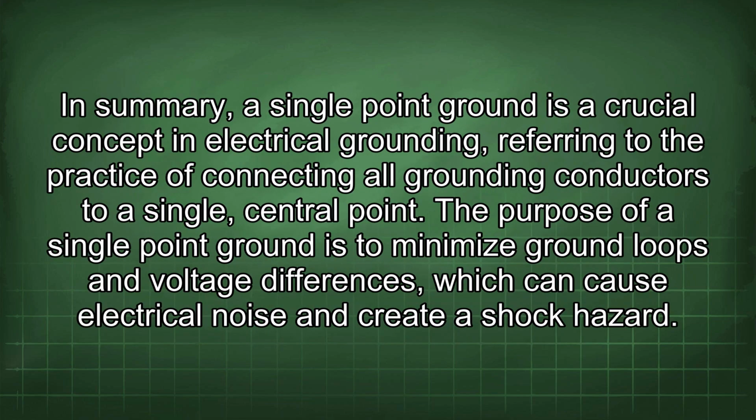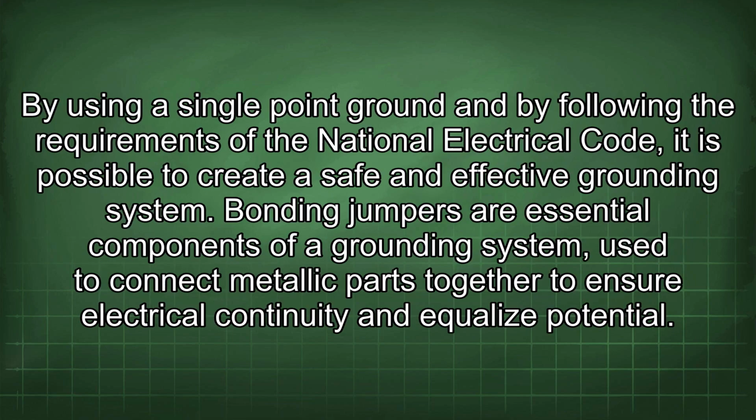In summary, a single-point ground is a crucial concept in electrical grounding, referring to the practice of connecting all grounding conductors to a single, central point. The purpose of a single-point ground is to minimize ground loops and voltage differences, which can cause electrical noise and create a shock hazard. By using a single-point ground and by following the requirements of the National Electrical Code, it is possible to create a safe and effective grounding system.